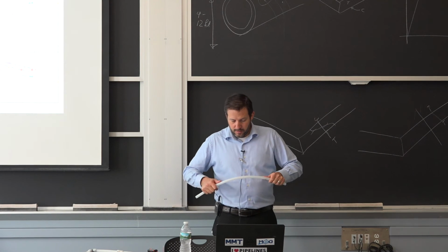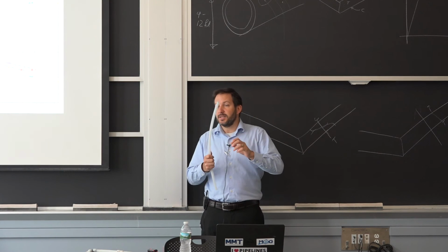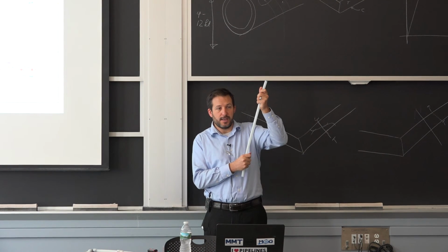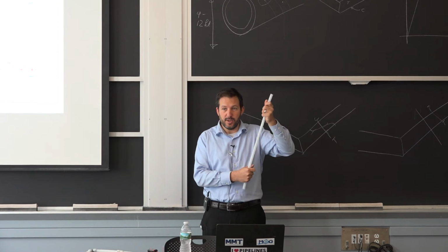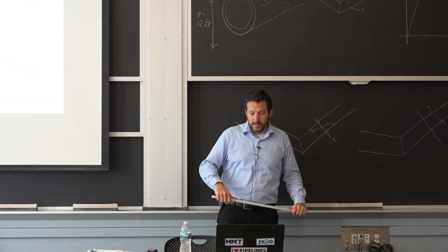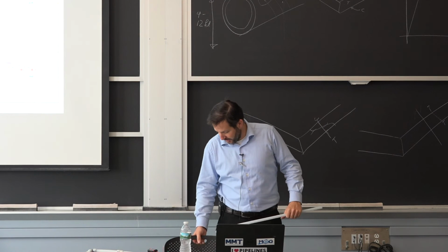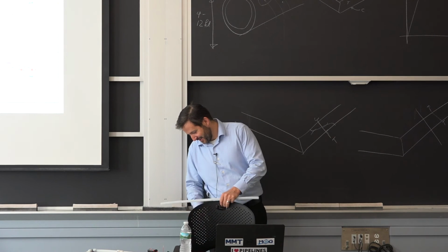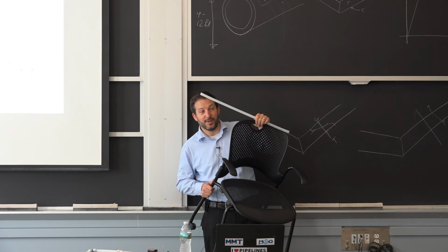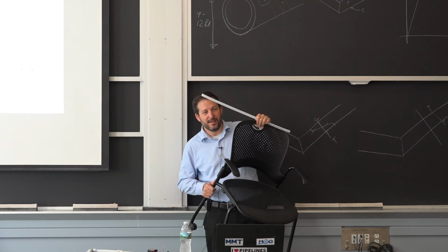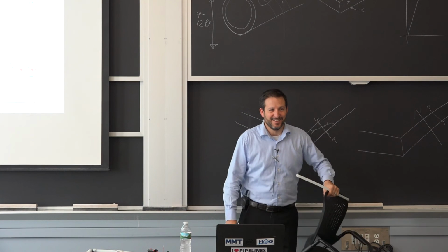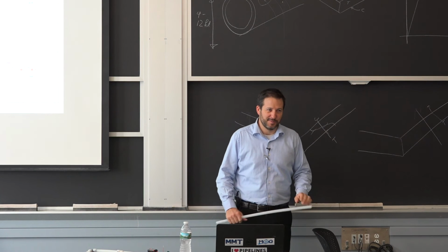It will creep. So this process that we discussed for steel when it's red hot and I pull on it and it gets longer, that happens at ambient temperature with most plastics. And it's one reason why there's a lot of applications like this, which is not a bad one. So we're assuming here that you won't sit on the chair forever, because otherwise it will sag on you, that you're going to be staying for 1 hour and then you go walk to another classroom.